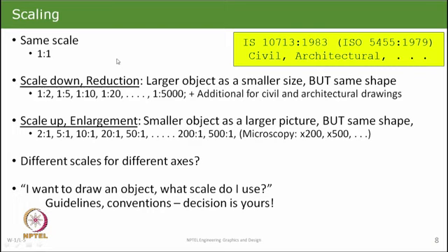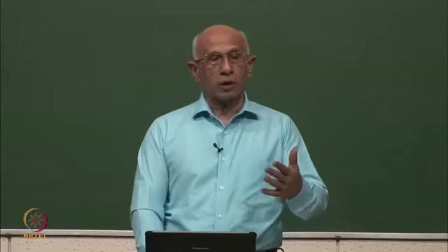But for mechanical engineering drawings, we have the following options of scales. Theoretically, we can have any scale, but the simplest one is scale 1:1. That means, on the picture we show every dimension exactly the way the real object is, and this is a true view. If we looked at the earlier slide, the tapering view is not used. It is good for visualizing, but is not good for engineering drawing.